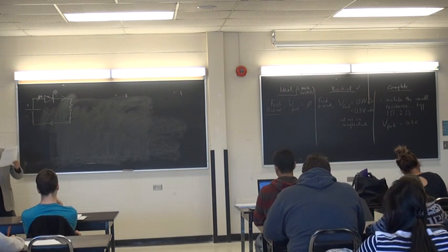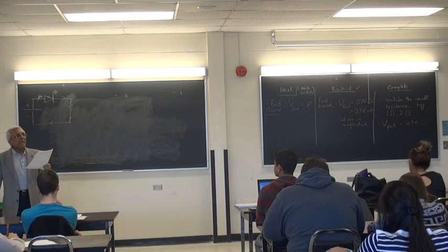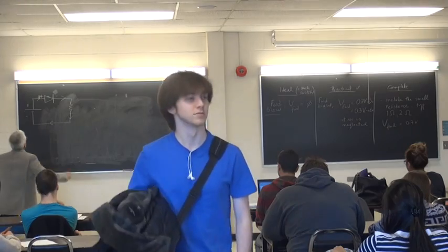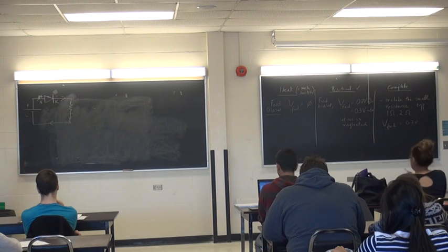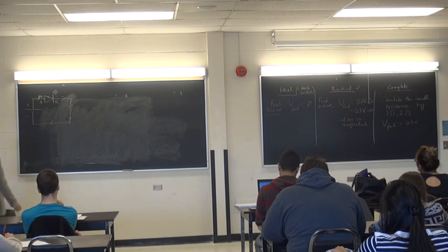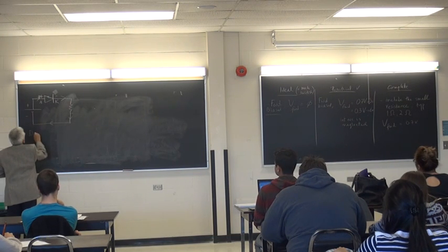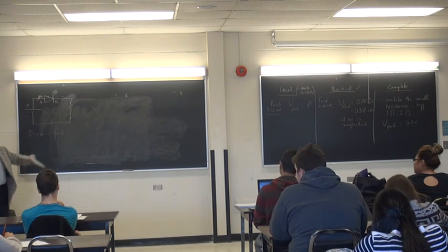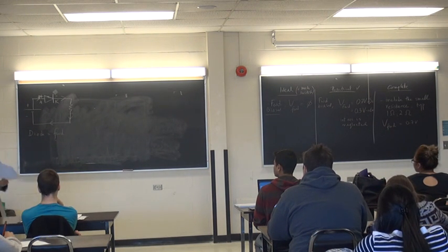And what does the hint say? The hint says A of the anode. A of the anode is the arrow. K of the cathode is the vertical line. So there's my A, there's my K, and as long as the anode voltage is more positive than the cathode side, anode is positive, cathode is negative, therefore we say that the diode is forward biased, which means that it acts like a closed switch with a 0.7 volt drop across it if I'm using a practical model.